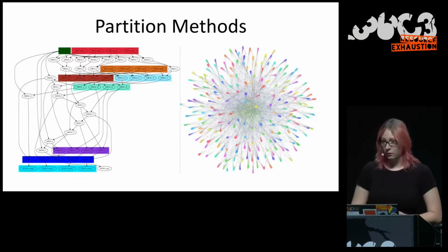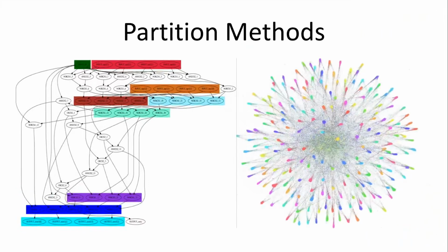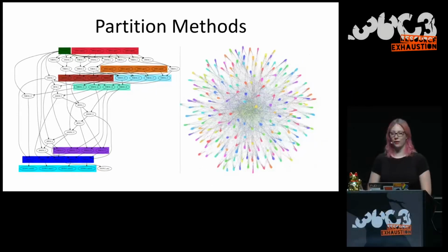The other thing you can again do is graphical analysis. So this is actually a fully parallelized AES implementation, which you can tell by the fact that it has 200 S boxes. Please don't write your AES like this unless you really have to, because it's very easy for us to find. It looks exactly like this. The 200 spots you can see are exactly these S boxes. And if you do graphical analysis, you will find that they're more densely interconnected, and you can get these kind of images, which are actually pretty easy for you to see. So if you ever start clustering a design and it looks like this, that's probably an AES.